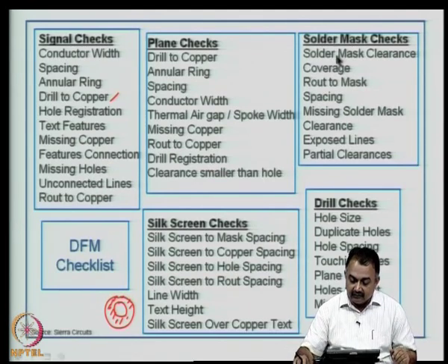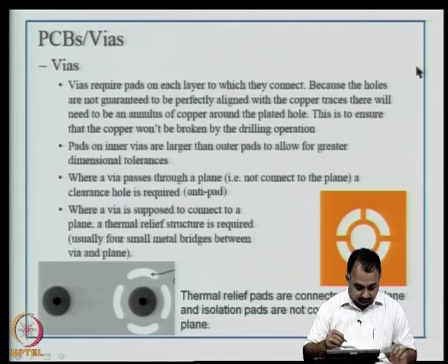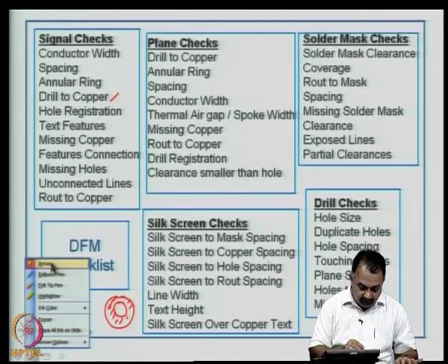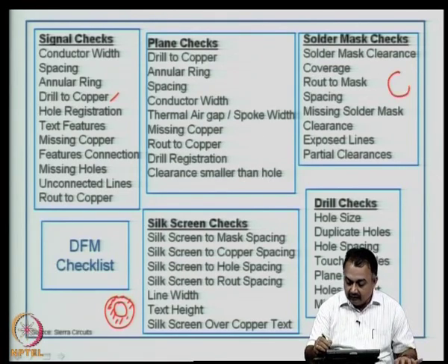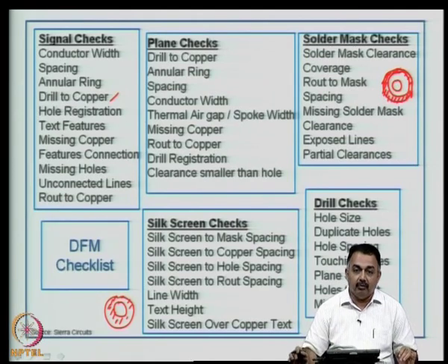When you use a solder mask, which is basically used to prevent bridging on the top side and bottom side of your final board, you have to look at what is known as a solder mask clearance. The solder mask clearance is usually about 5 mils. So, if there is a pad and this pad needs to be open, finally this is the drill, you will have a third area which we call a solder mask clearance, which means the solder mask will not cover the copper area.